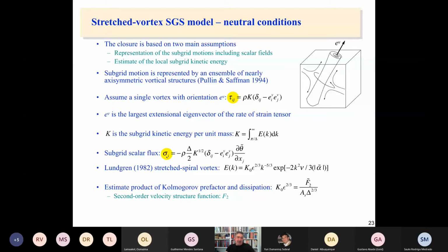So this vector on the left and the vector on the right have the same direction. But here, this guy is a tensor. It's a second order tensor. So the sigma and the d theta dx vector, that is the resolved scale gradient of your scalar in the turbulent field, are not aligned, okay? This is very nice. You can see that the model has this built-in anisotropy. And when you compute all of these terms, you can do it on the grid scale. Everything is local and dynamic.